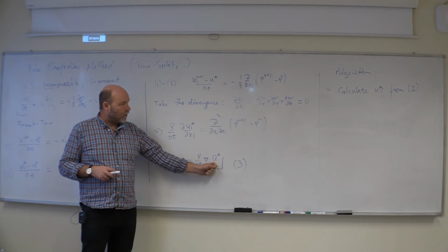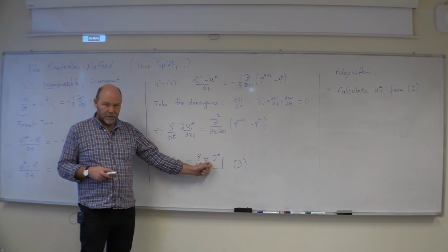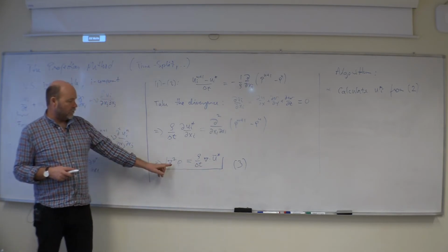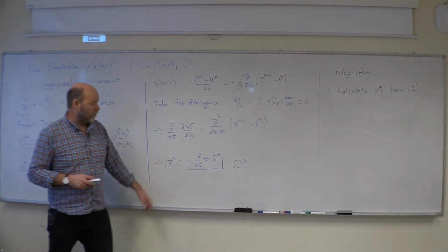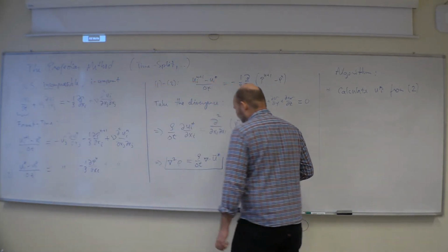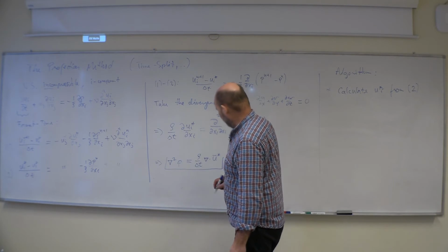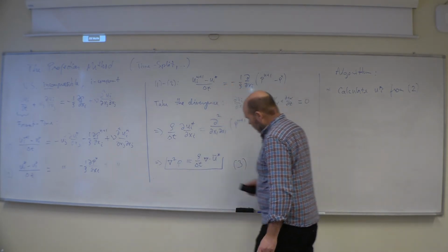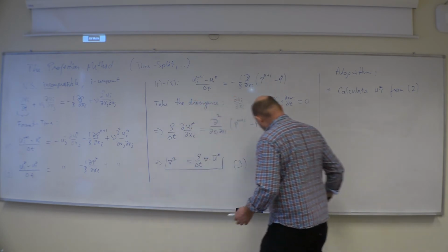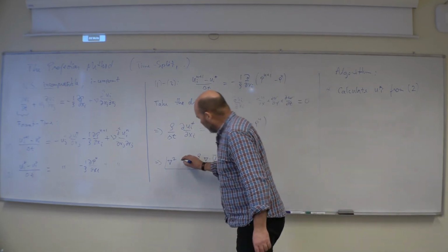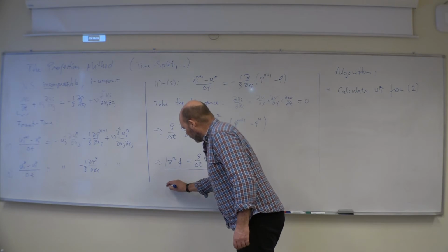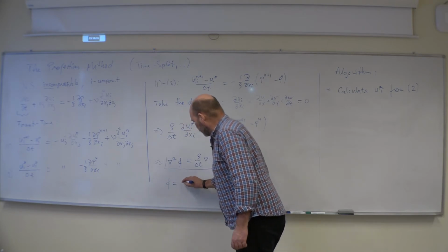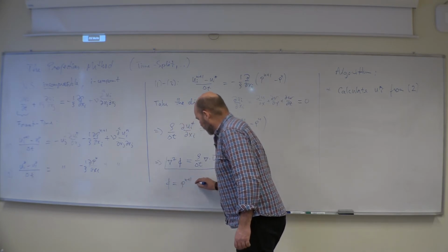We have the U star velocity field. We can calculate this divergence. And then we have a Poisson equation for the pressure. I shouldn't write P here, sorry. That was wrong. I think in the notes I used a scalar function phi, where phi equals this pressure difference.